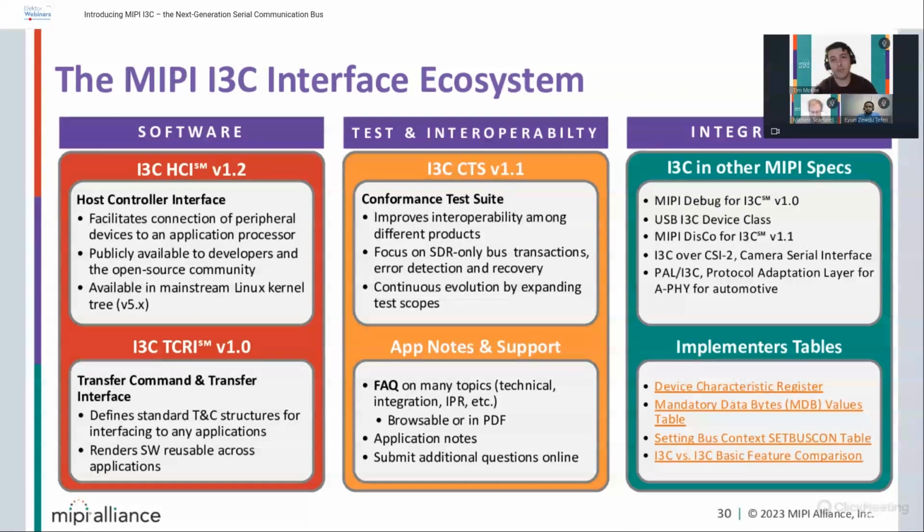As far as the test side, we put together a conformance test suite. Basically, it focuses on the SDR bus, but gives implementers a set of tests to run that can help prove the correct implementation of their design. We also have a bunch of app notes, support and FAQ, all to help the implementer tackle some of the commonly known questions and some of the more difficult areas of the specification.